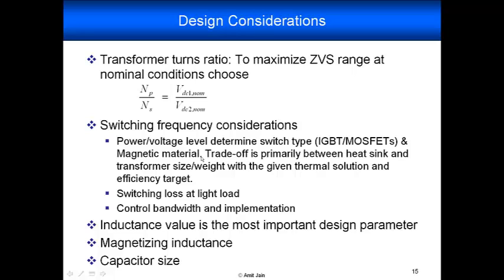And the trade-off here is between the heatsink size, the transformer size and weight, and the efficiency target for a given thermal solution. So the heatsink and the transformer size and weight will depend significantly on how you actually cool your system.